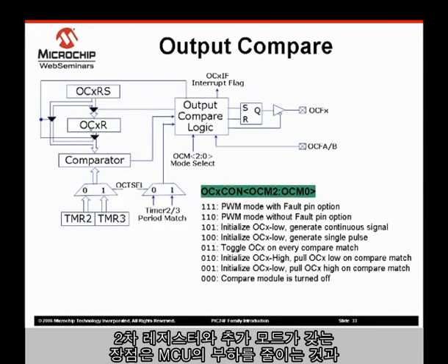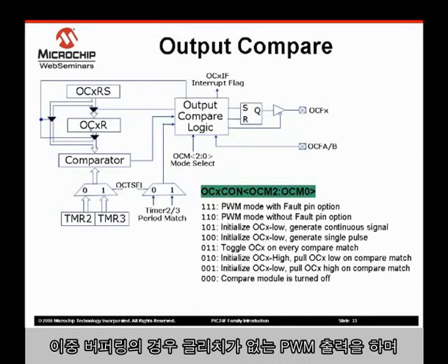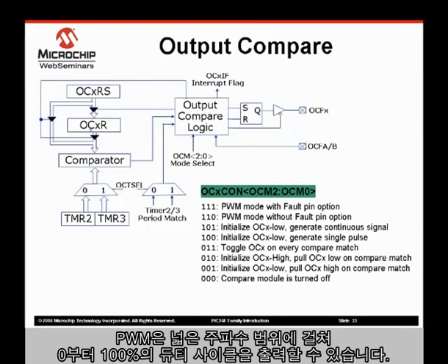The benefit of the secondary register and the additional modes is that the load on the MCU is reduced, and very short pulses can be generated because there is no need to load a second register. The double buffering allows glitchless PWM output. The PWM can now cover a full range of 0 to 100% duty cycle over a large frequency range.